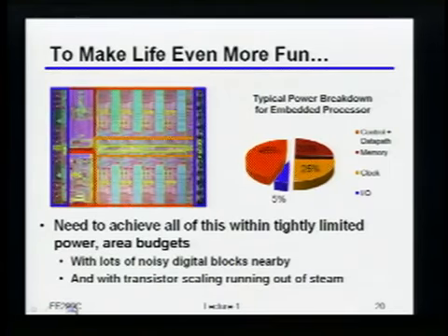Oh, and by the way, like I'm showing on this picture, this is the Cell processor. These blue things, those are actually the IOs. That entire rest of the thing right there, which dissipates about 100 watts or so, that's all some big, nasty digital block that likes to do whatever the heck it likes to do and creates a couple hundred millivolts of noise on the supply, can easily create volts of common mode variation between different points on the board, and so on and so forth. Okay? So the message here is that it is actually a pretty tough thing to do.